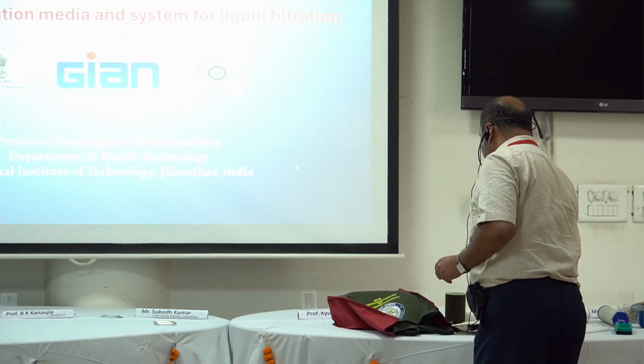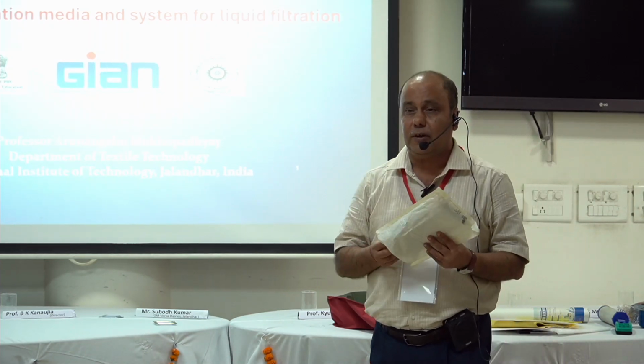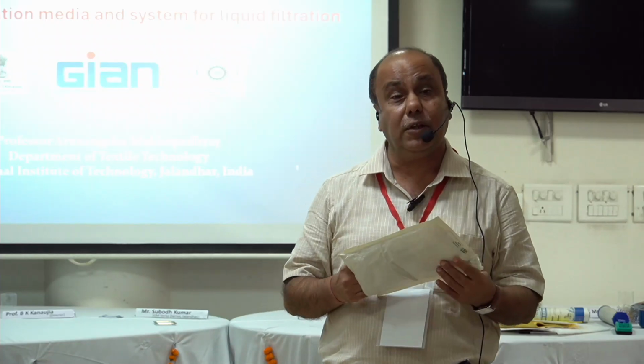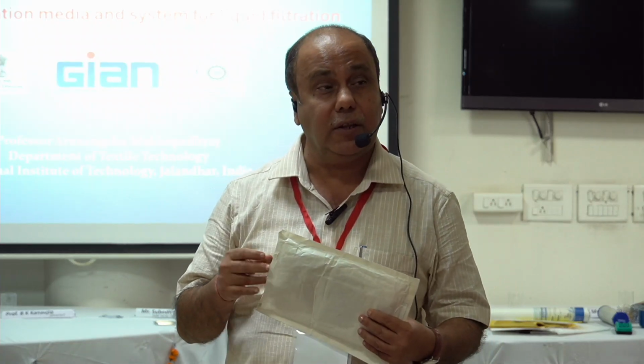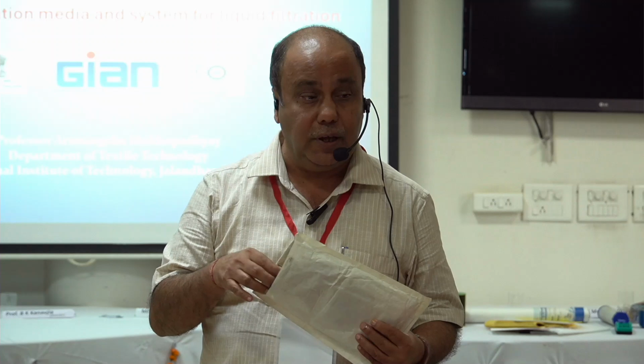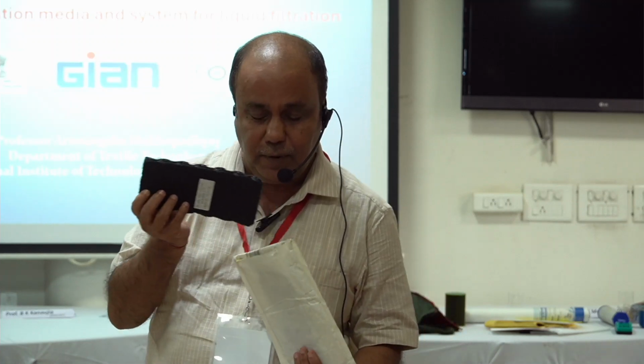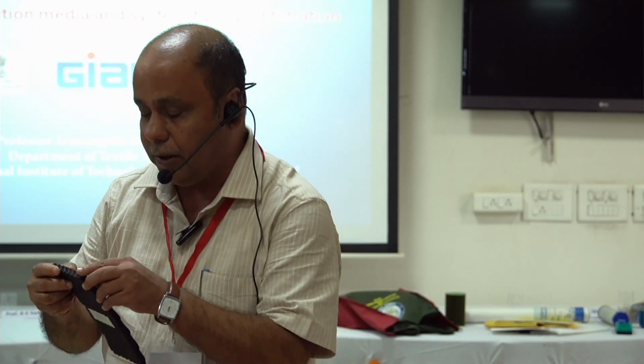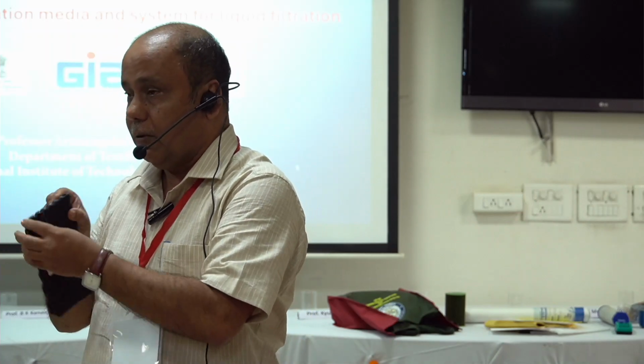Now, if you look at the broader sense, even in the geotextile we are using the concept of liquid filtration. It is not that only in industrial application we go for liquid filtration, but if you look at the geotextile, there also the concept of liquid filtration is valid. If you see this composite material, inside there is a plastic core, and outside the non-woven material is there. So whenever the liquid flows, this is used for underground drainage. Whenever liquid flows, it will filter because we are using the media.